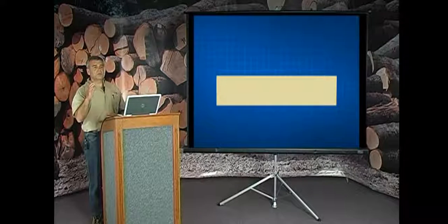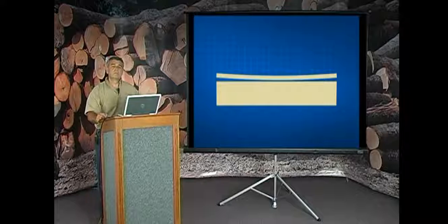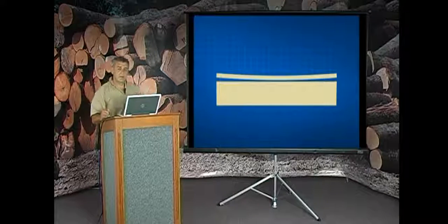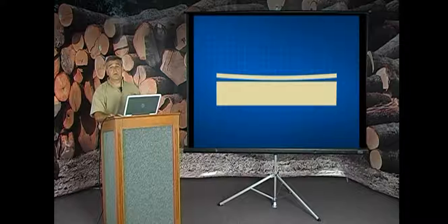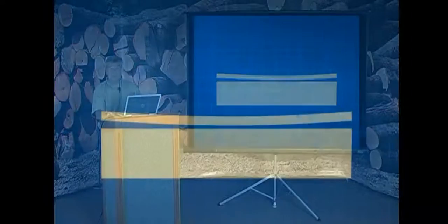So let's just say you've got a cant on there and you drop 2 inches and make a cut, and you recognize that that board that you're cutting is starting to lift on the ends. It's trying to do what we call face bend. Well, I assure you that the cant is also trying to move. In some cases, the cant will behave and won't move much at all. In other cases, it'll move a considerable amount.